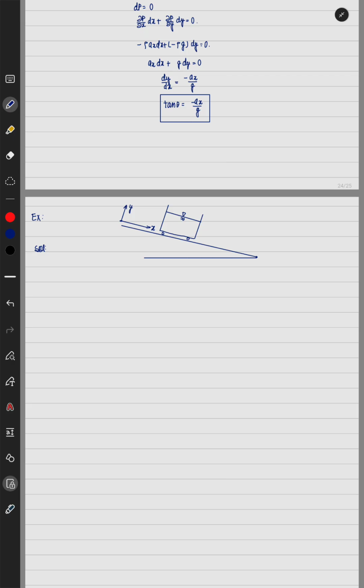Okay, again I will do the same process. For the surface I can write pressure is equal to constant, because pressure is equal to atmospheric pressure. So the change in pressure is equal to 0. Del p by del x dx plus del p by del y into dy is equal to 0, and minus del p by del x plus rho bx is equal to rho ax. Acceleration in x direction is given by,